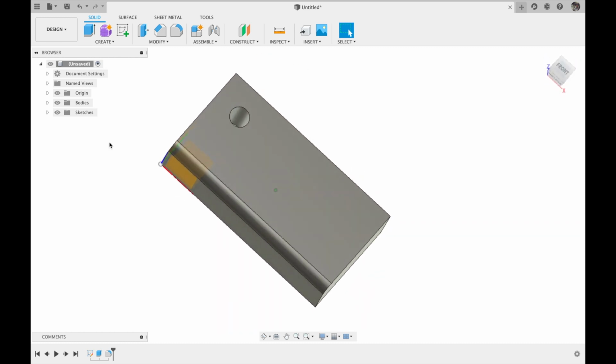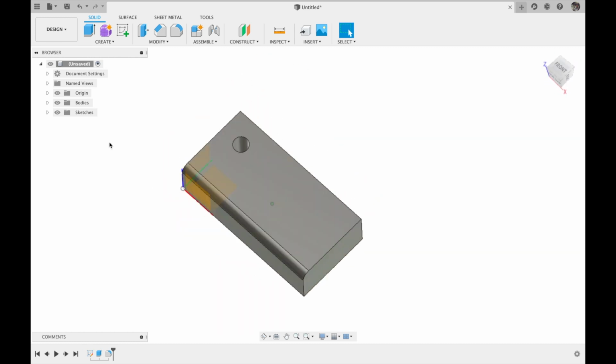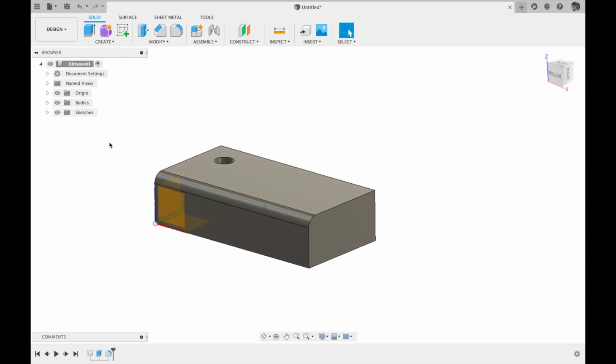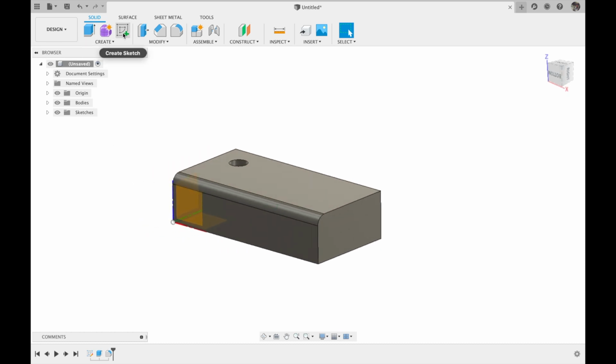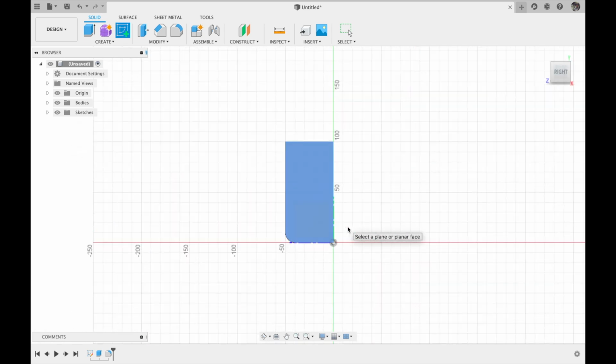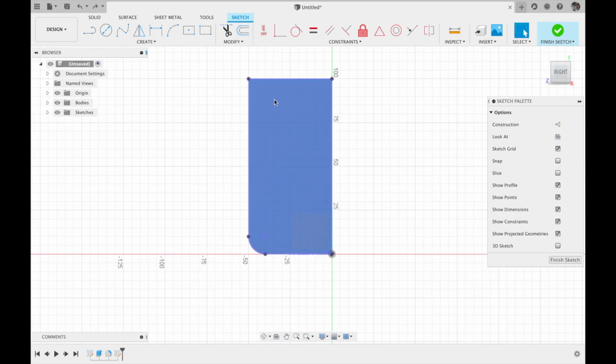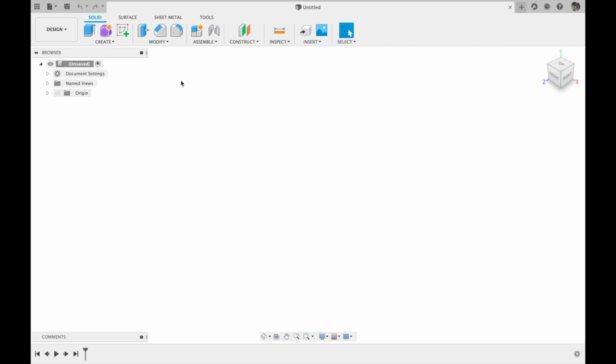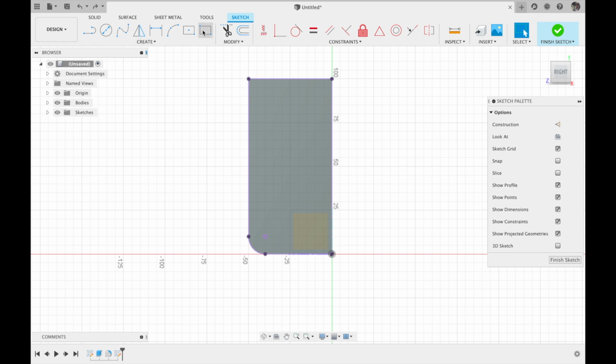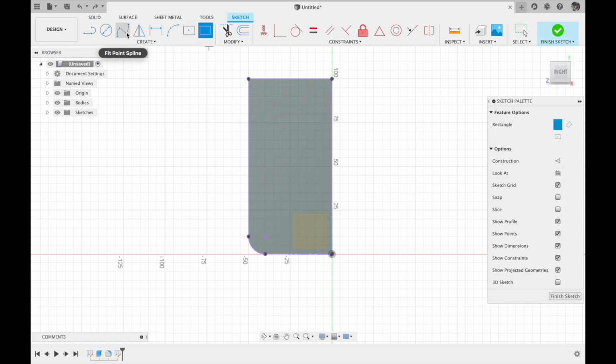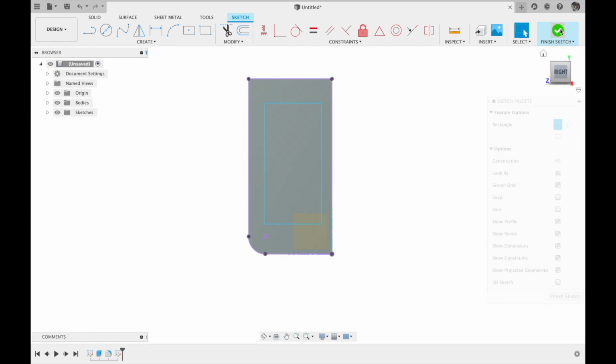Now you can add some more features to your part, and to create this, you can go back to the create sketch function, click on one plane for example. When I like to add a hole or other features to my part, I can use the sketch tool also. For that I click on one of the features at the top, draw my box, click on finish sketch.